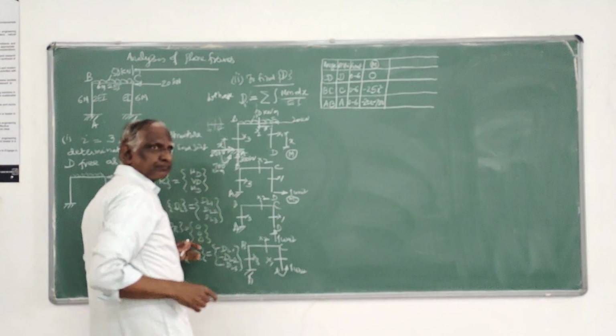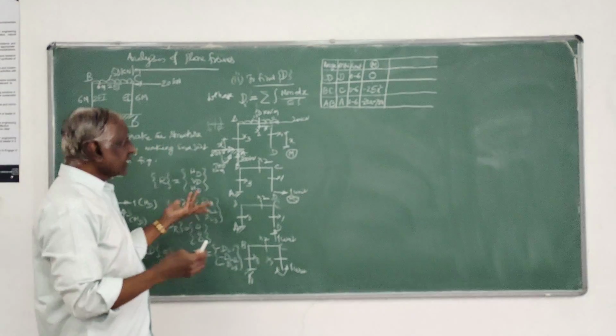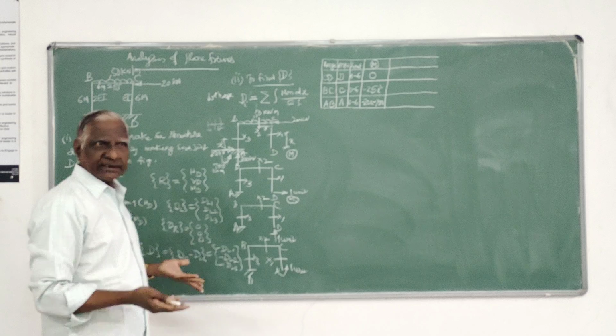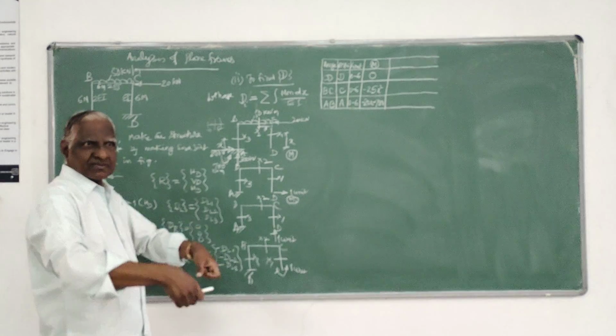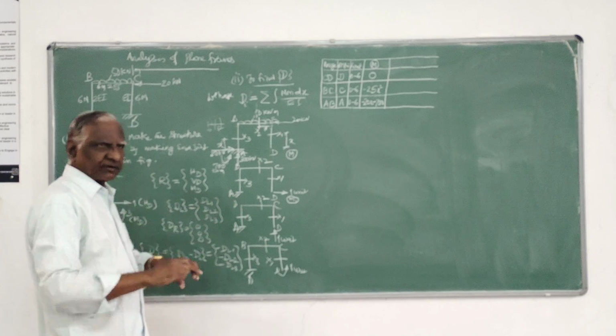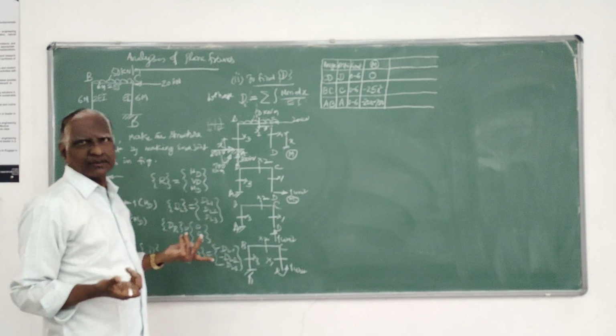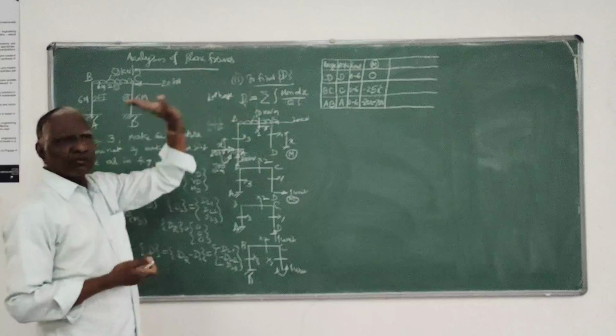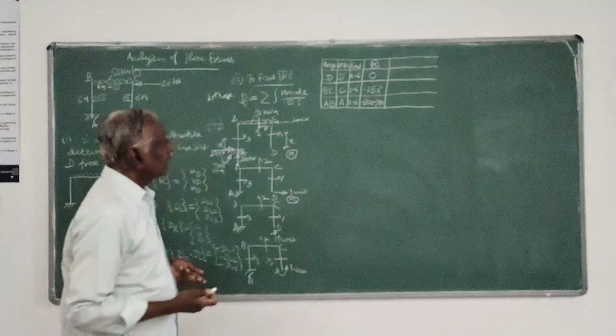So the sign convention we have to remember is the usual beam sign convention: load giving a sagging type of moment is positive, hogging type of moment is negative. Let us follow the same sign convention. That's all.